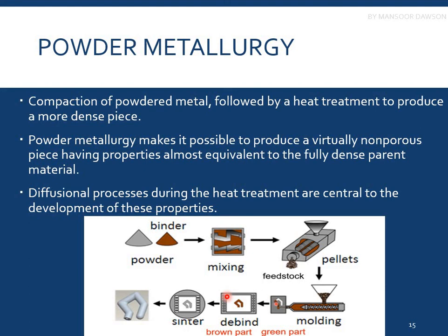And then we do sintering, in which we get the diffusion of the two metallic powders. If you are using two different metals to make an alloy, the two metals are bonded and mixed together by diffusion, and the binder joins itself, and the part is finally sintered, and you can achieve a solid part. So you can achieve many intricate shapes from these powder metallurgy techniques.